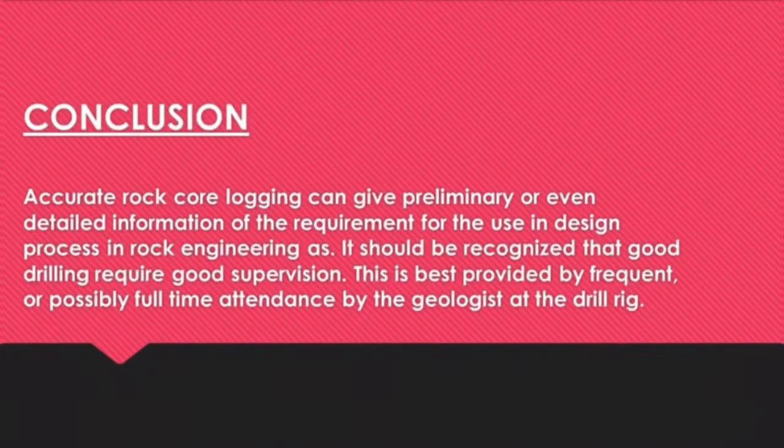The conclusion of the core logging test. Accurate rock core logging can give preliminary or even detailed information on the requirements for use in the design process in rock engineering, as it should be recognized that good drilling requires good supervision. This is best provided by frequent or possibly full-time attendance by the geologist at the drill rig.